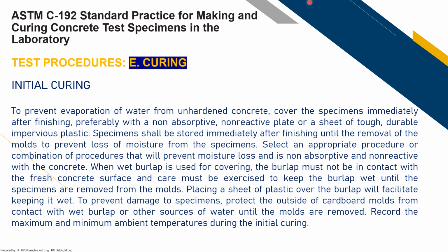For the initial curing, to prevent evaporation of water from unhardened concrete, cover the specimens immediately after finishing, preferably with a non-absorptive, non-reactive plate or a sheet of tough, durable, impervious plastic. So you need to cover it. Specimens shall be stored immediately after finishing until the removal of the molds to prevent loss of moisture from the specimen.